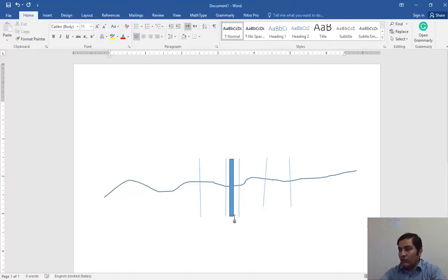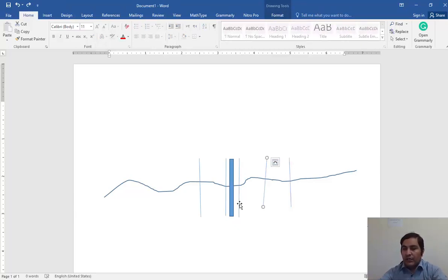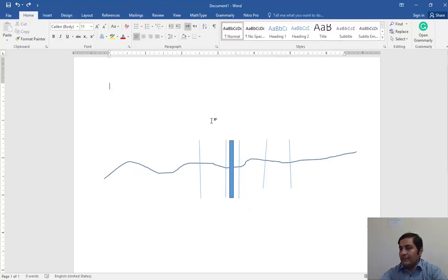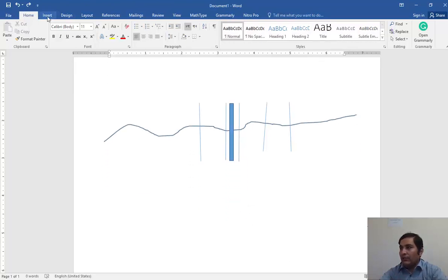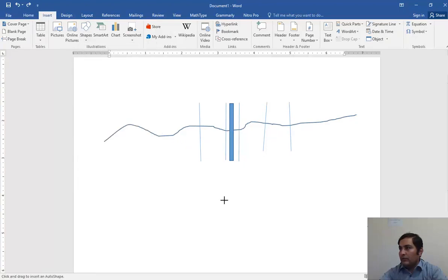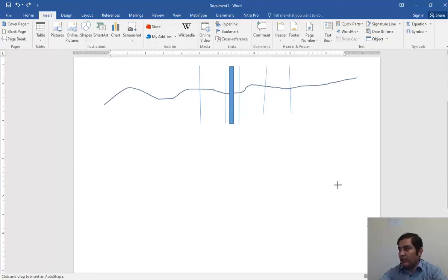Remember that if you want to model each structure, you should have a different cross section. You should define different and appropriate cross sections around upstream and downstream of your structure. Okay, this is the plan, and I want to create a shape of the cross-sectional shape.